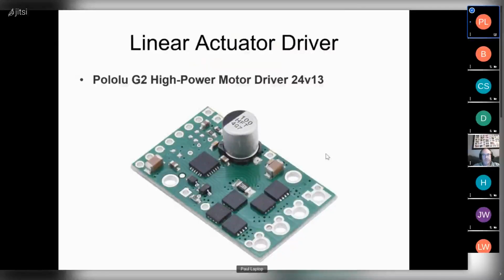So once we've detected what layer we're on, the goal will be to try to keep that laser on it. This detector will be mounted on the trailer, rigidly attached to the blade. As you move the blade up and down, the detector will move up and down across this plane of laser light. The goal will be to adjust the linear actuator so that the laser light stays on, say, the fourth layer of the detector. If it's too high, we'll move it down. If it's too low, we'll move it up.